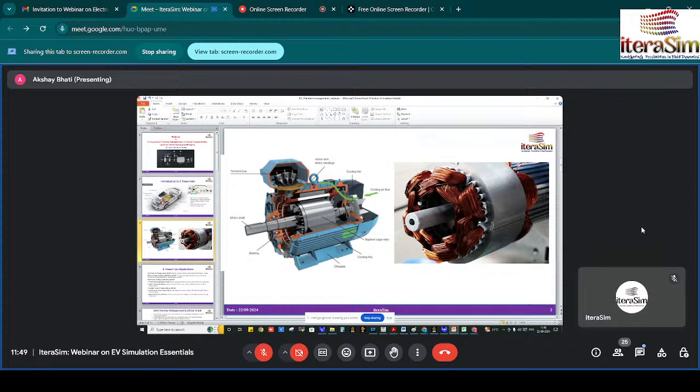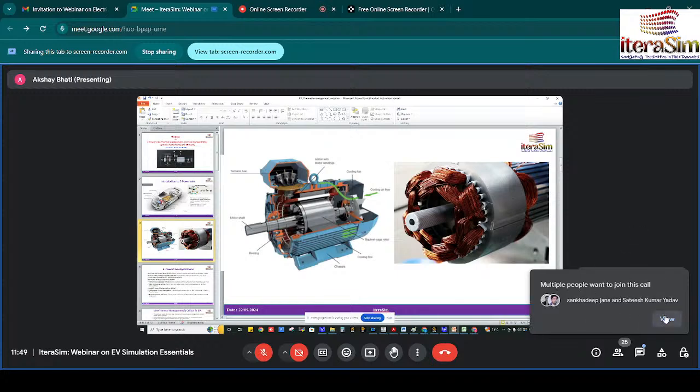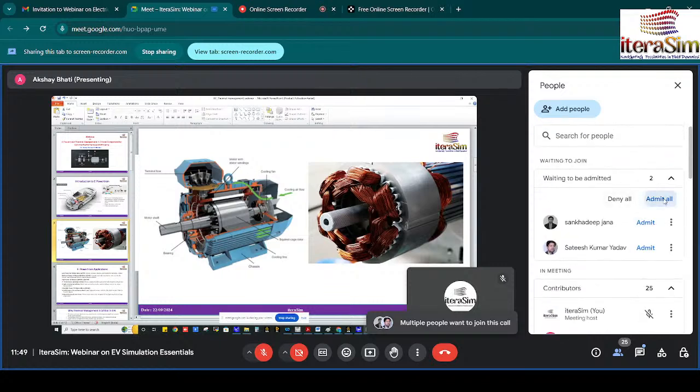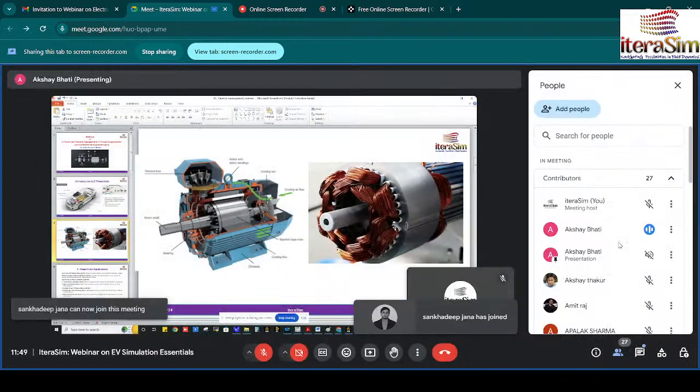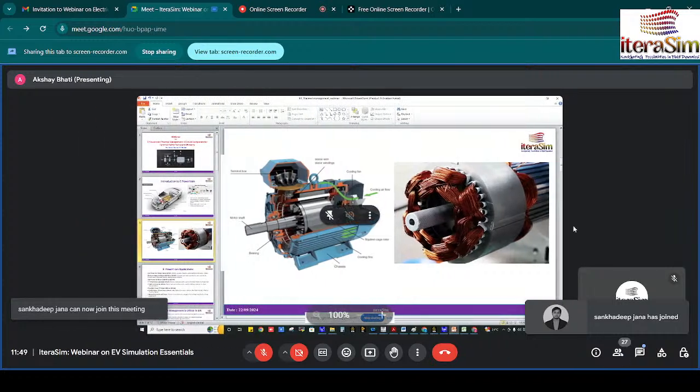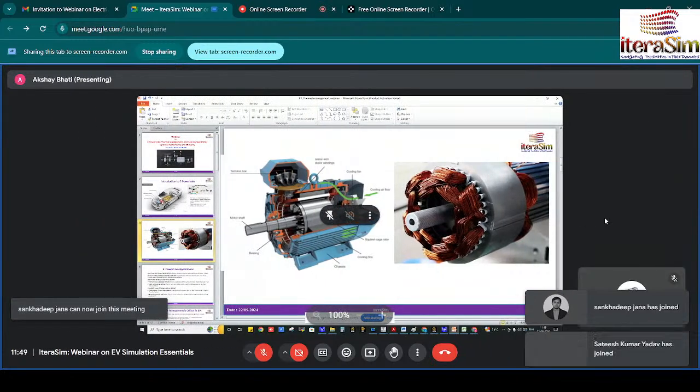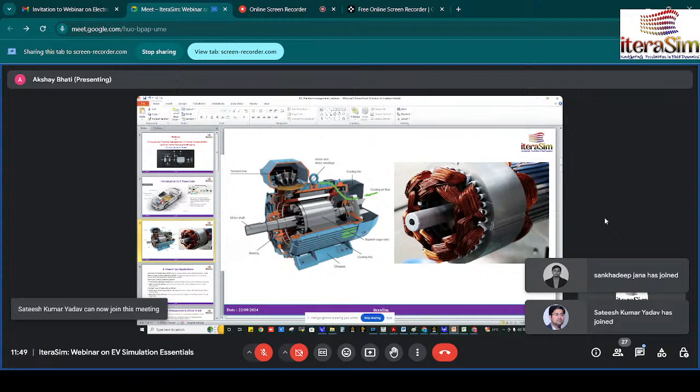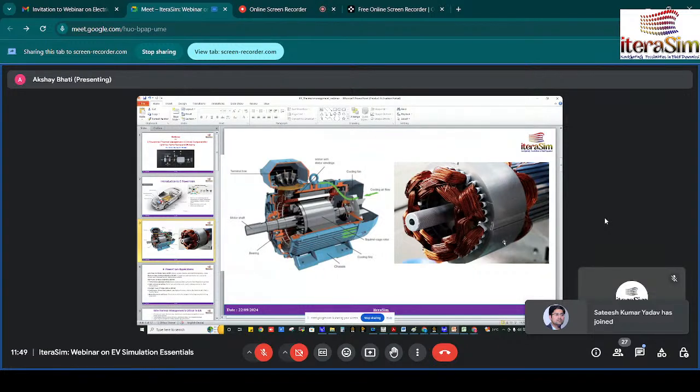It is non-electrically conductive, and its thermal conductivity is also relatively low. So you can see that the end winding doesn't have good conduction heat transfer, since it conducts the heat through some insulating material. So it is necessary to dissipate the heat from the winding, otherwise it will fail, or it will degrade drastically with time.